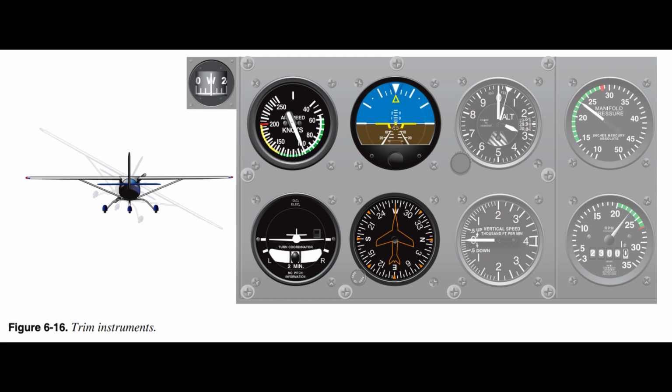An aircraft is placed in trim by: 1. Applying control pressures to establish a desired attitude. Then, the trim is adjusted so that the aircraft maintains that attitude when flight controls are released. The aircraft is trimmed for coordinated flight by centering the ball of the turn and slip indicator. 2. Moving the rudder trim in the direction where the ball is displaced from center. Aileron trim may then be adjusted to maintain a wings level attitude.